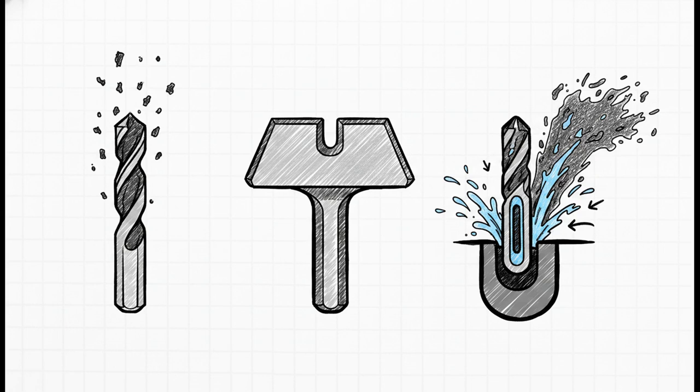And when you're making those initial holes, you have some highly specialized options. The twist drill is your standard go-to choice, featuring spiral grooves called flutes to guide chips upward and out. For large diameter holes, you might use a spade drill just for its sheer stiffness. But honestly, the engineering of the gun drill is absolutely brilliant. Because chip disposal and intense heat are massive challenges inside a deep, closed hole, the gun drill uses built-in, high-pressure coolant passages running right through the center of the tool. This violently flushes out the metal chips so the tool doesn't jam up or melt.